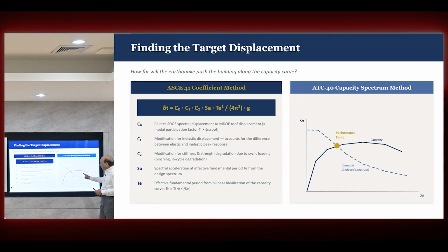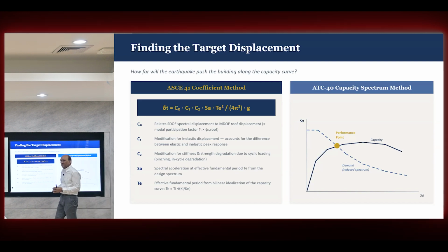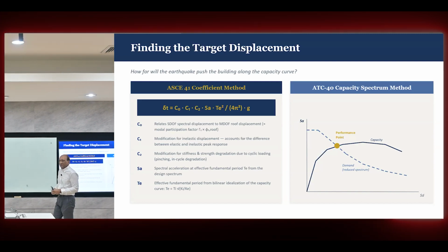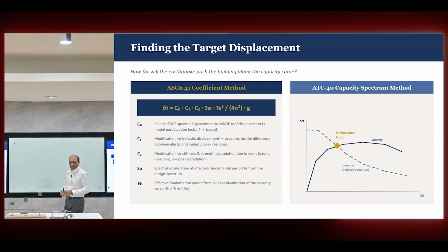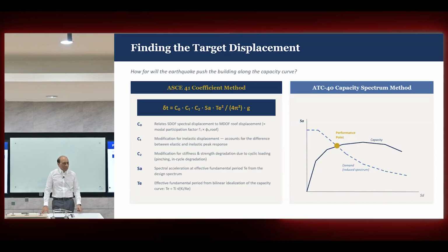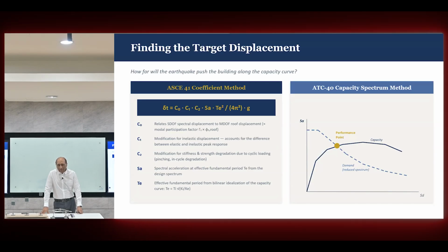Or the earthquake is here and the demand is very low, over-design. So you can check all those things by comparing the scaled response spectrum and the actual push from 0 to failure together, and then you can get all of the important information.